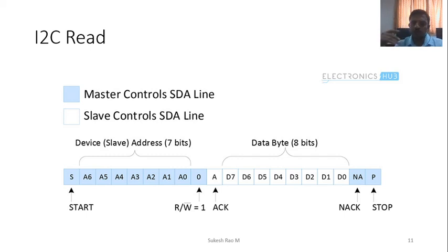So this is a brief introduction to I2C, and I2C is a general topic. MSP430 has an I2C peripheral, which can be accessed by accessing the respective registers. One thing you need to understand is the protocol. If you know the protocol, then with any processor you take up, you can handle I2C communications.